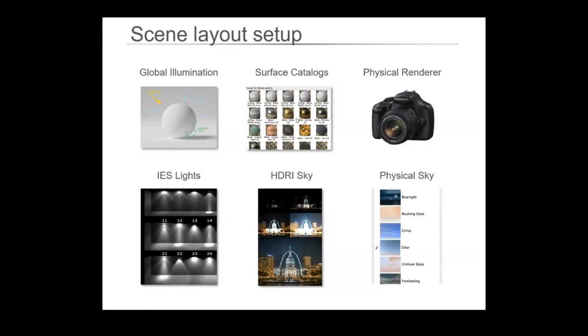Like these golds and brasses and these metallic ones. So the default material that you might bring in from somewhere is not necessarily set up correctly for rendering purposes. So it's always good to go in and double check in the background with the material that you're going to use to see how it's set up. Quite often you'll find it wanted a dull matte finish, so got to keep that in mind.